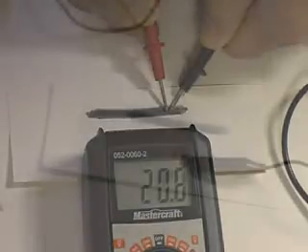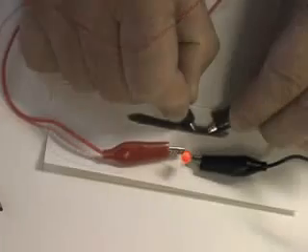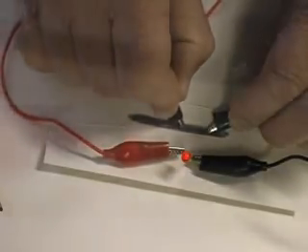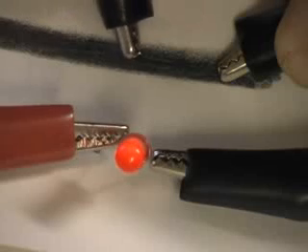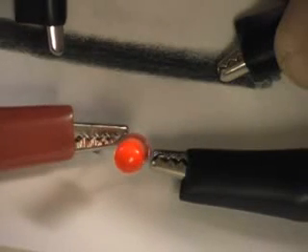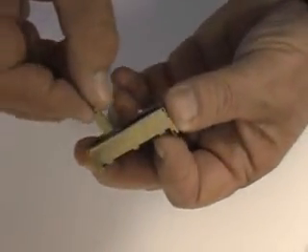Using this pencil lead resistor in a circuit with a battery and LED, we can see the effect. Sliding the contacts controls the brightness of the LED. If you try this, be sure to use a suitable current and low voltage source for the LED. Excessive current could damage the LED. You could be injured.